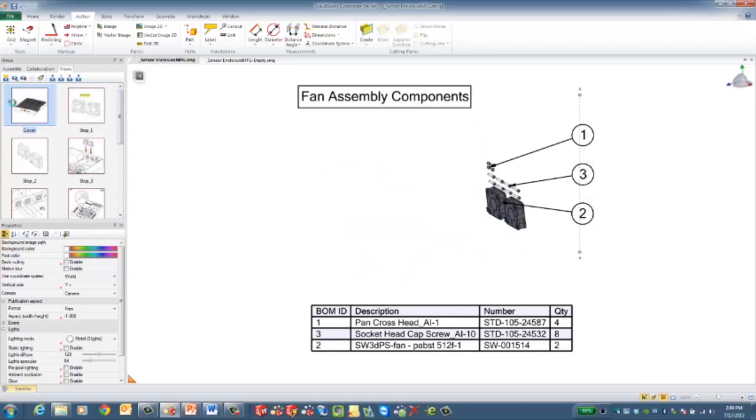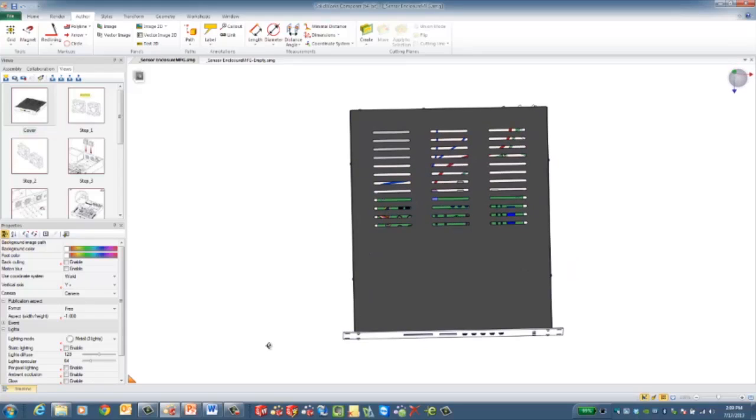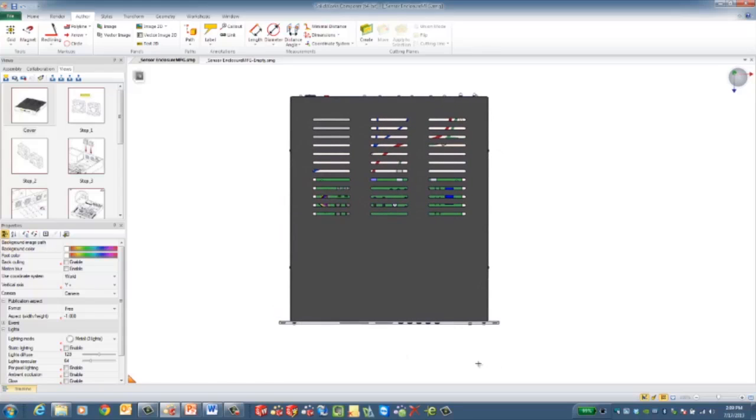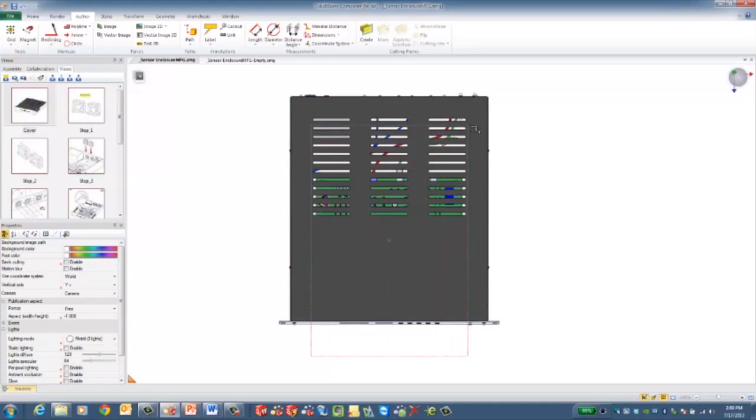So how do we do something like that in a traditional CAD package? It'd be very time consuming. For those of you who've used CAD before, you would know that creating a view like that is very tricky, and different parts might be in different sub-assemblies, and just lining things up and moving things around is very challenging to do with a traditional assembly structure. So let me take you through how to create a view like that using SOLIDWORKS Composer.